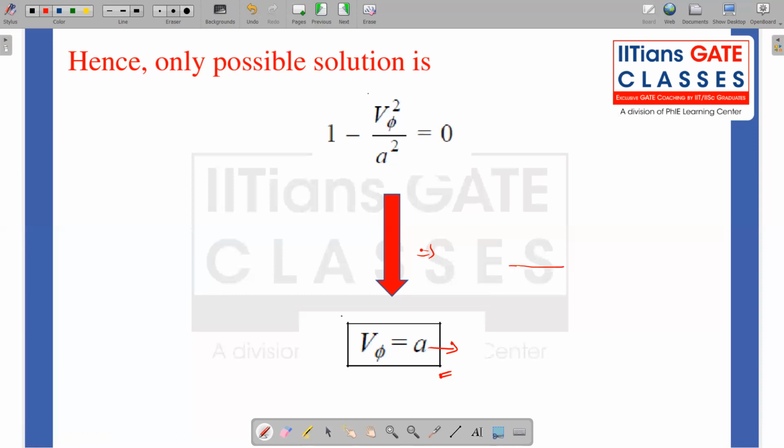So like this, where the flow has to go through a series of compression. So still we can get an expansion compression corners, through which when the flow is going through, these can result in a constant entropy process. So that means even the compression can happen in an isentropic manner. It is actually theoretically possible. Practically, we can design with a very minimal total pressure loss.